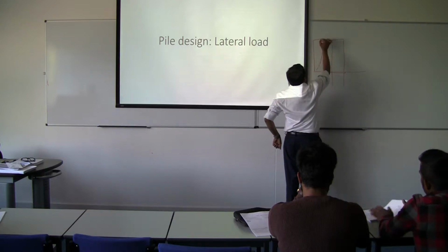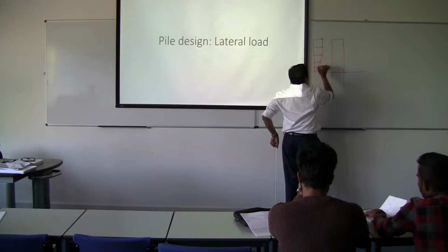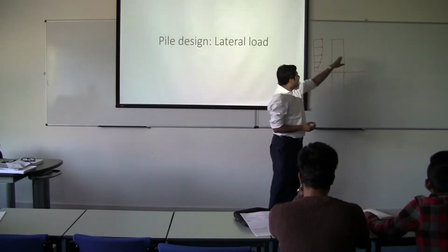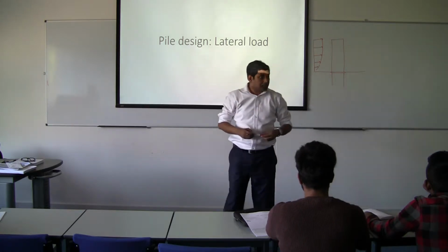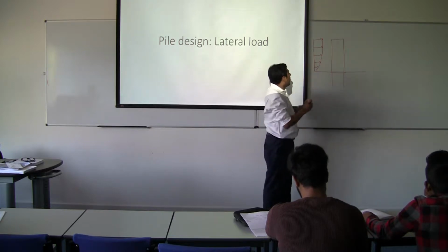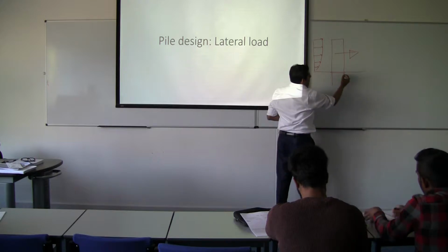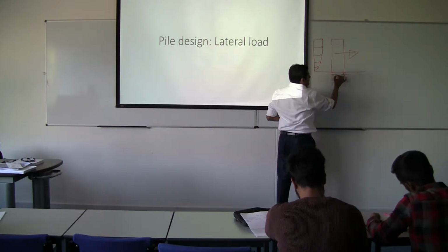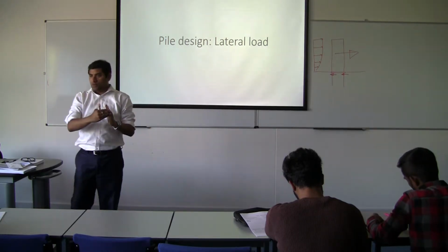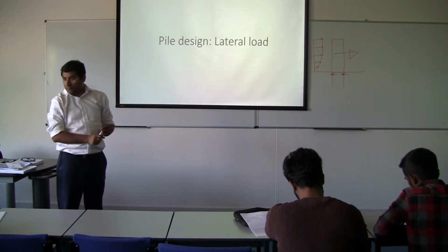If you know the wind speed, you can find out the thrust, and when you know the thrust, you get a lateral load acting on it. So who will take the lateral load? This is applying a big load there, so these piles will take these loads, isn't it? So there will be a reaction. Somebody has to resist the lateral load, otherwise it will move.